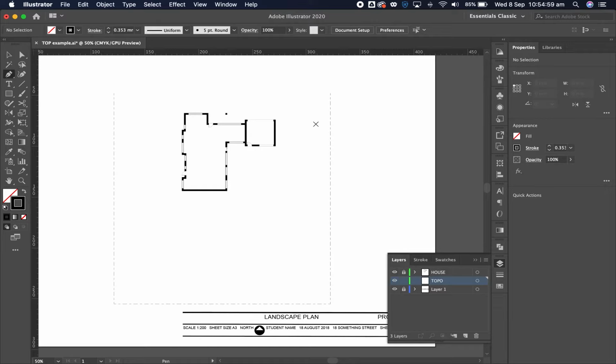So I'm going to have mine as a 500 millimeter increment. Okay, you could be different in yours. If you want to be more exact, you have 250 millimeter increments. If the land that you're using is flatter, then I'll probably go to 250 millimeter increments. If it is quite a slope, I'll probably go to 500 mil increments.